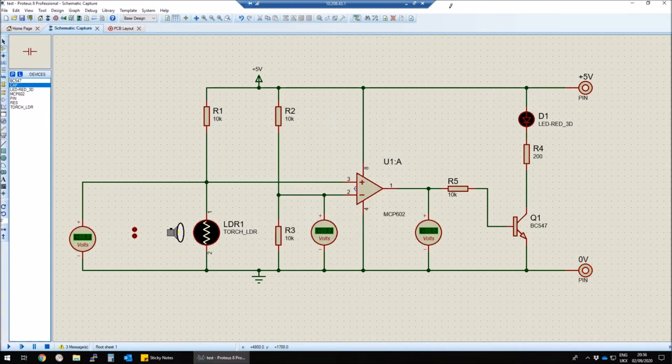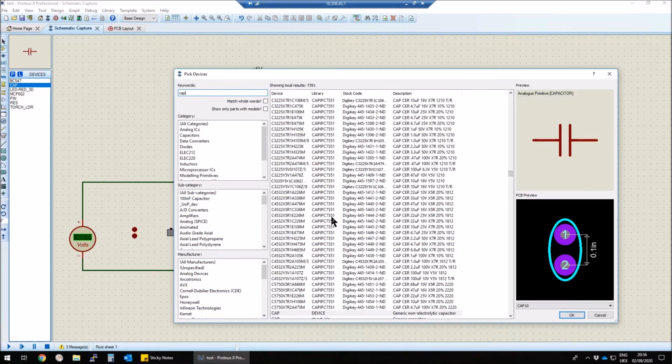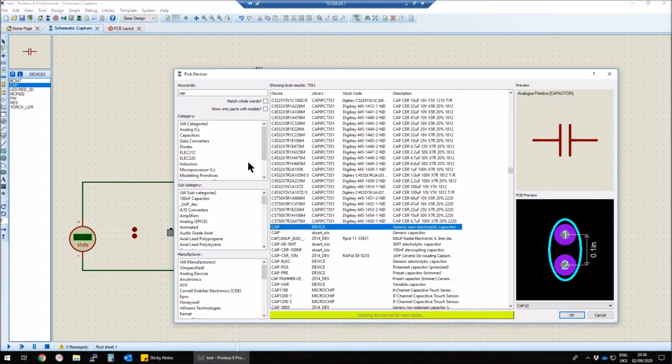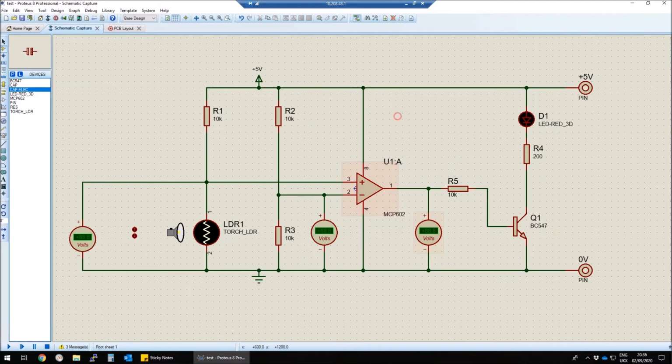Op-amps can be sensitive to noise on the supply rails, so I will add some decoupling capacitors on the supply rail to filter the noise away. This is especially important if the op-amp is being used in a low noise or high gain application. In order to filter out a wide range of noise frequencies, I will use a 100 nanofarad in combination with a 4.7 microfarad. The 100 nanofarad will filter out the high frequencies, while the 4.7 microfarad will filter out the lower frequencies.